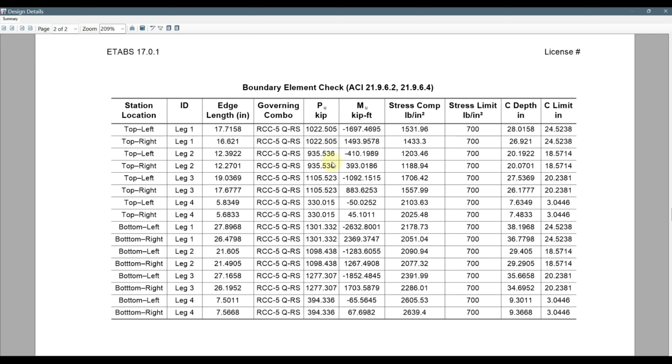However, for vertical element design, I choose to use 100% scaling. And for beam design, I choose the 85% scaling because I want to keep my beam design ductile, and hence I want to provide less reinforcement so that beam-column capacity ratio and similar issues do not arise, and my column doesn't become weaker due to higher reinforcement in the beams.